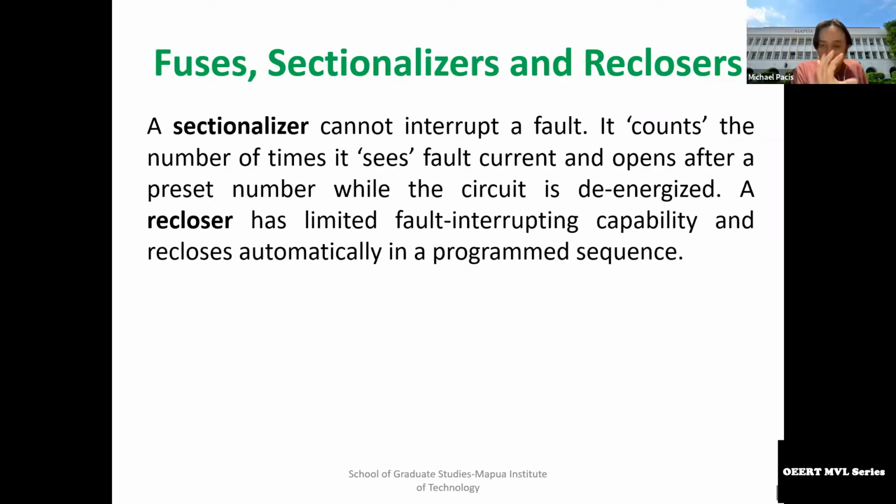And here, ang sectionalizer, please take note of the word cannot, they cannot interrupt a fault. It only counts the number of times it sees the fault current. Ayan, nakalagay naman dyan, you cannot interrupt a fault. Parang switch lang siya, sectionalizer switch, to be specific. It only counts the number of times, or in terms of frequency.